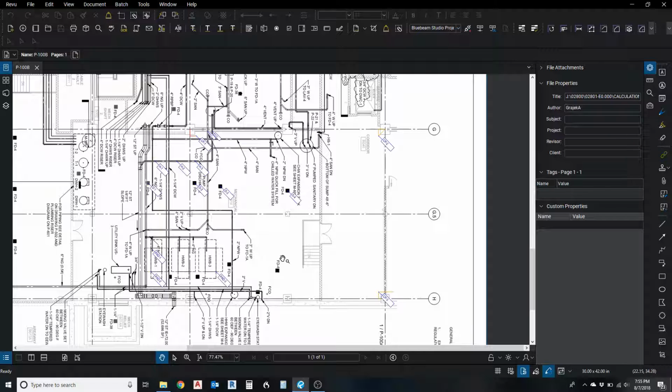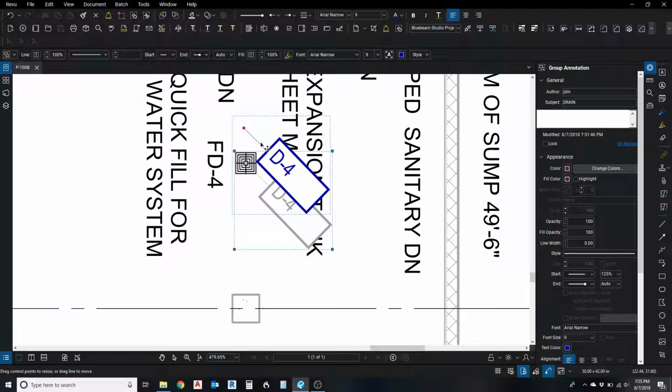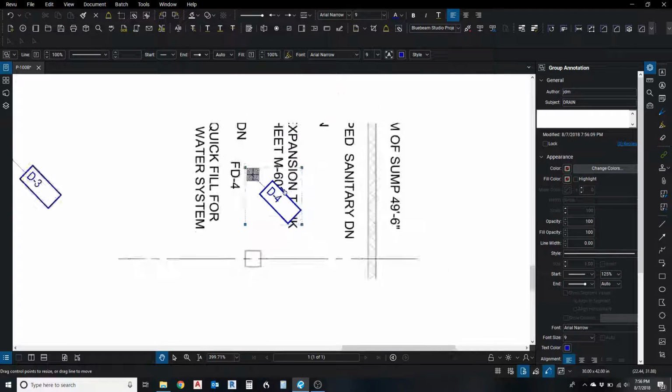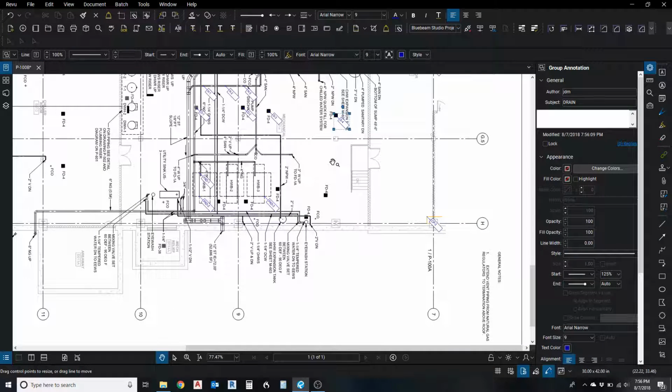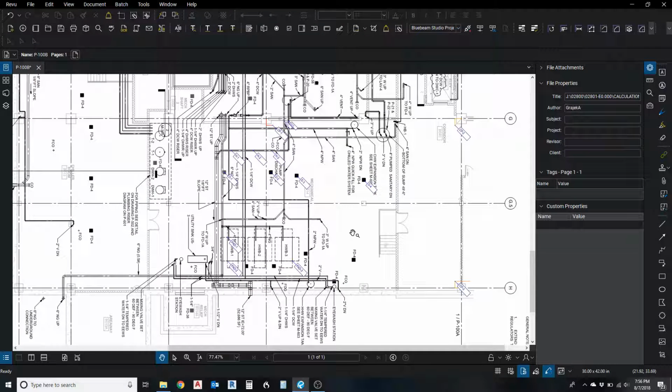Okay, so you want to save at this point, and if someone wants to add additional points, they can simply come back in and add additional points. The other thing they can do is move a point, all right? If they come in here and move, say, this D4 6 or 8 inches up, and they resave the CSV and load it into the Trimble, it's not going to make a new point. It's going to move that point 6 inches up, because that point is D4, okay? I want you to remember that. It doesn't seem important now, but it will seem like a big trick later when you're sending these points out to the field and the guys are saying, no, we don't want it there, we want it here. That's when you're going to want to know that anything moved in this drawing is a coordinate that is actually moving in the point file.